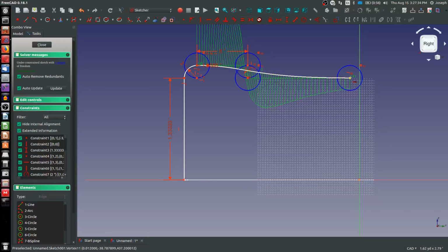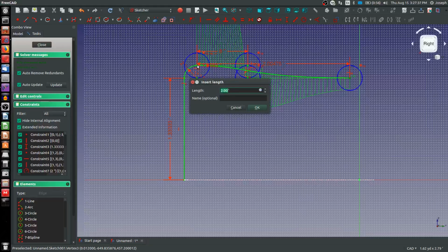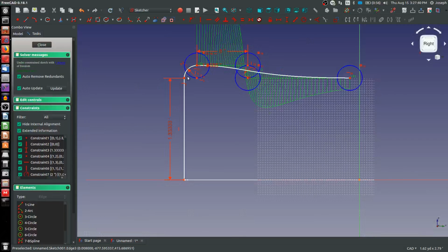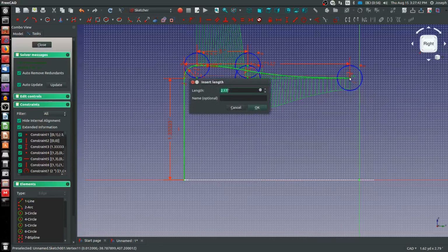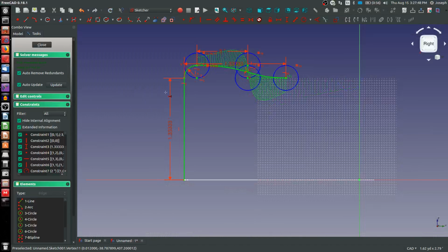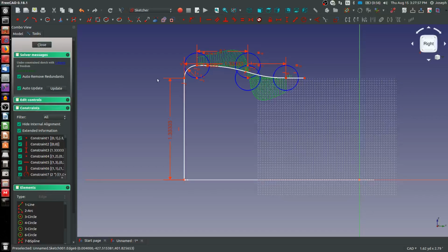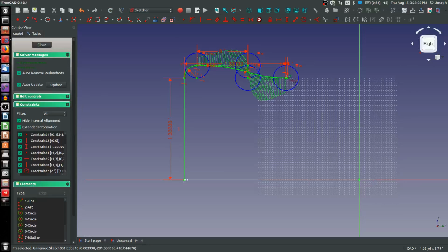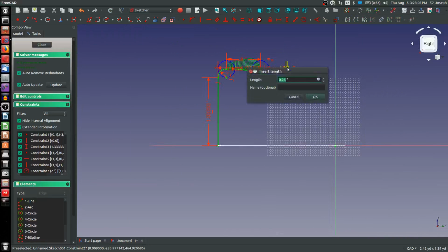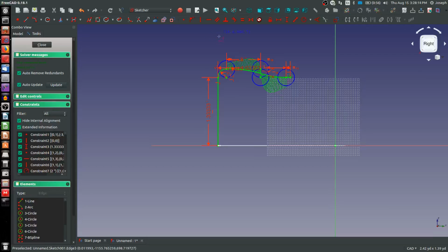And I'm going to take the end of my B-spline, actually no, I'm going to dimension from this front to the end of this and make it 1.3 feet. Now, I want to go into a straight line, and we can make that, let's make that 1/4 inch. You know what? I'm going to make that 1 inch. That seems good. And then let's make an arc.